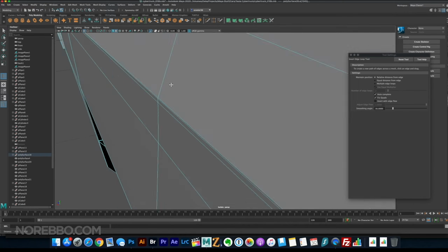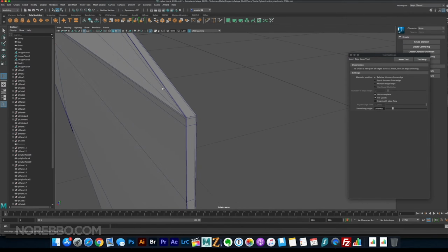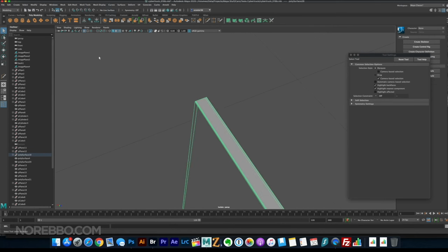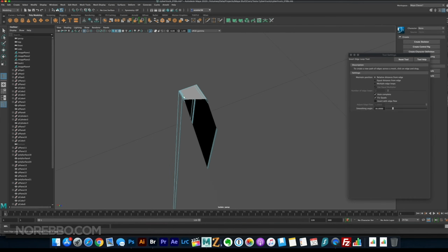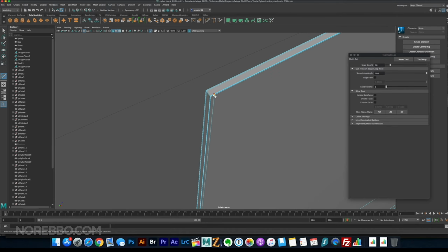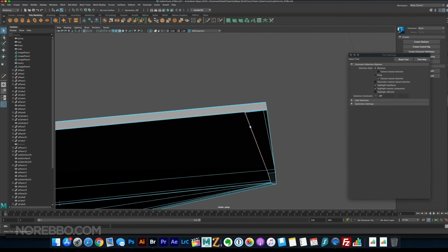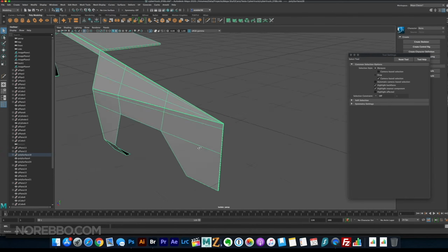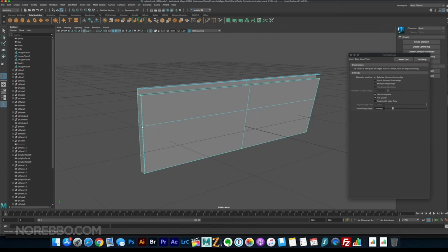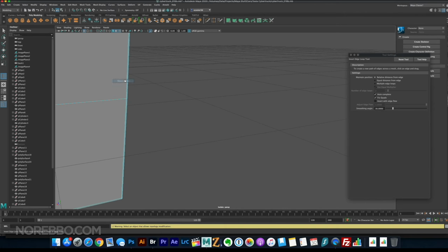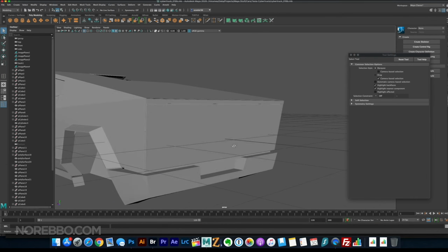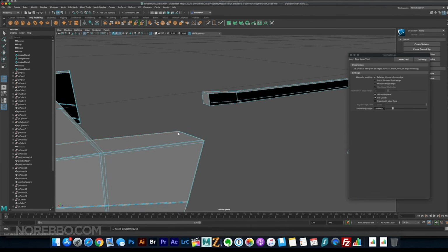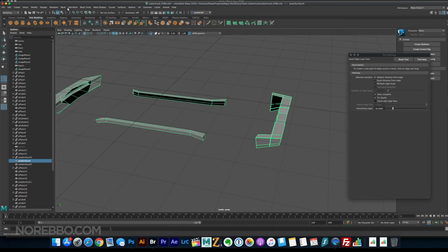And here I am mucking around with that back section again, and I've got all those edge loops coming together at that one point. Total nightmare. I totally goofed that up. And the perfectionist in me wants to go back and rebuild this model the right way, which is leaving the polygons untouched, unsmooth, and just beveling, instead of trying to add edge loops everywhere. So if you want to build a Tesla Cybertruck of your own in 3D, do not smooth it. I imagine that most people wouldn't, because the Cybertruck is so angular anyway.